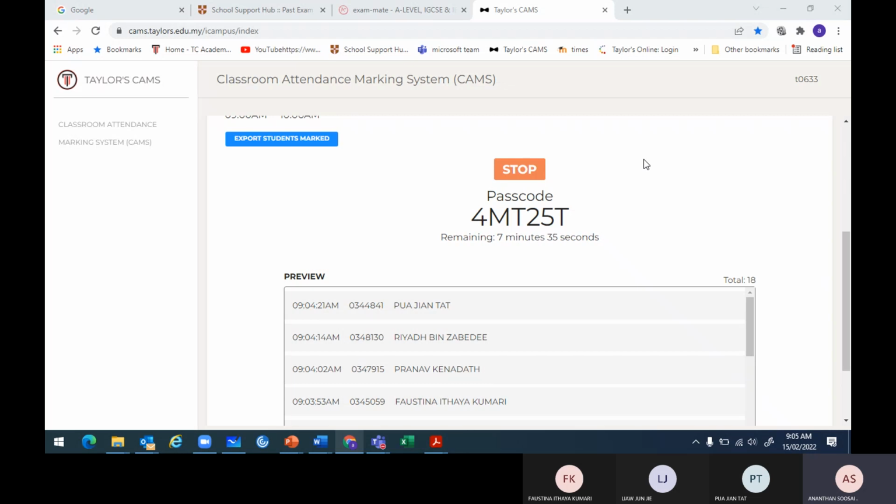So that's the highlight of this topic. I_RMS is I naught over root 2, V_RMS is V naught over root 2, for a sinusoidal wave. For any other shape, like a square wave, you square the graph, and I told you what to do, right? Then rectification towards the end. Last class we did that. We use a diode, then we use a capacitor for smoothing the output. Okay, so let's go through some past papers today.